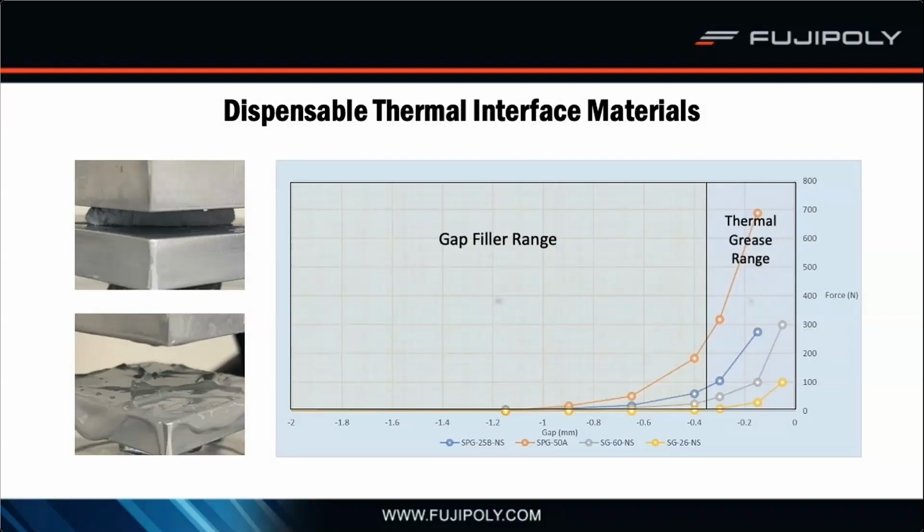In fact, only a small force is required to break up the contact resistance. The small force used to compress the gap fillers is enough to do that. Once it's at the gap, there really is no pressure needed to be applied after that. And again, to emphasize something, we really want you to understand the thermal interface you're working with, and make sure that you're selecting the appropriate material for that interface.